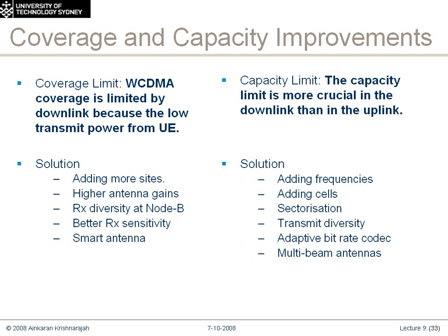Some other techniques are called adaptive bitrate codecs. For example, the voice codec in 3G is called AMR, or adaptive multirate. The AMR codec in 3G actually has 8 modes that it runs at. It starts at 4.75 kilobits per second and goes up to 12.2 kilobits per second. Most network operators are running at 12.2, so it's quite good speech quality. However, it typically tends to run at 4.75 in congested networks.